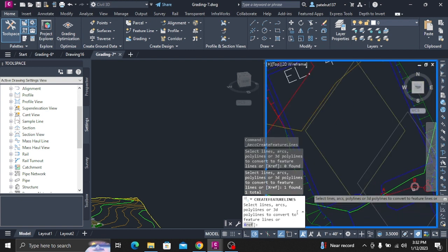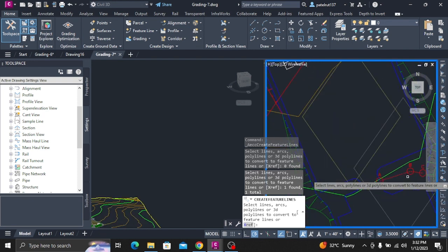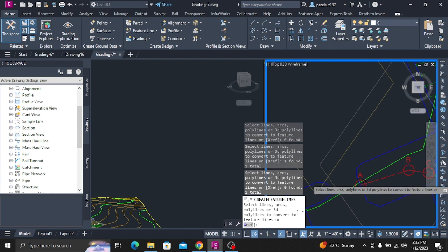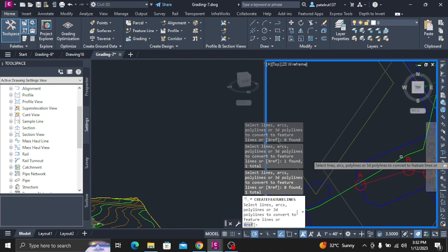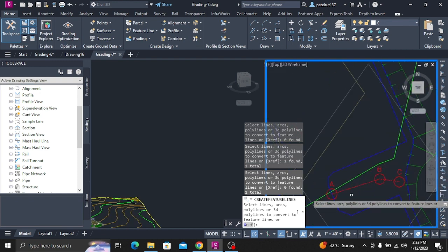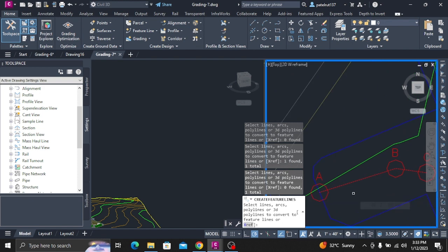In the Grading Elevation Editor, in the row, change the elevation value to 400.00 foot. In the right viewport, select feature line ABC. Using the grip inside Circle A, move the beginning point of the feature line toward the lower left of Circle A. Note: you may need to hover over the feature line, and then use Shift plus spacebar to select the feature line. Right-click the feature line.